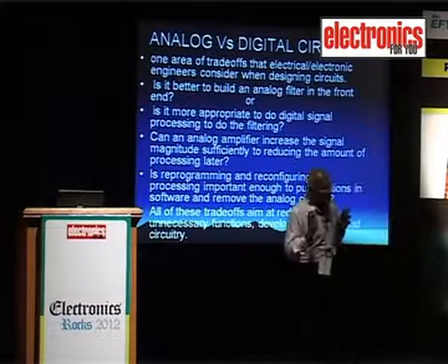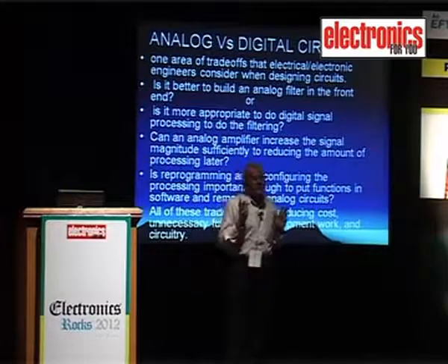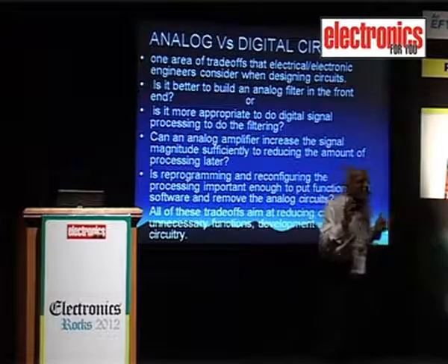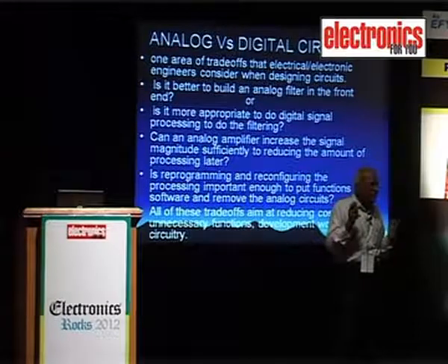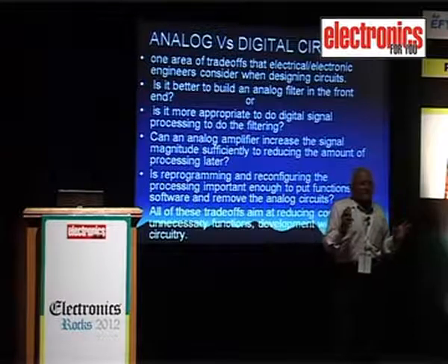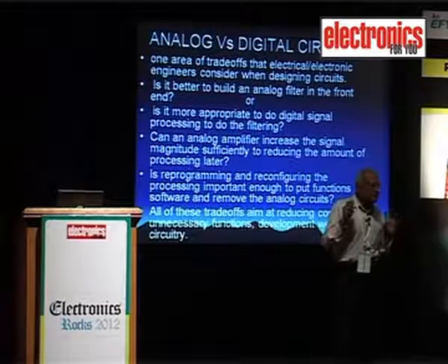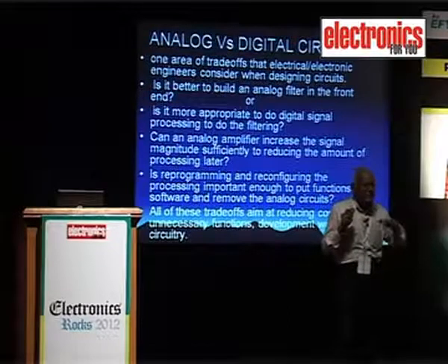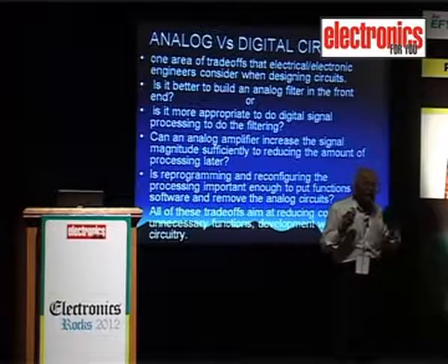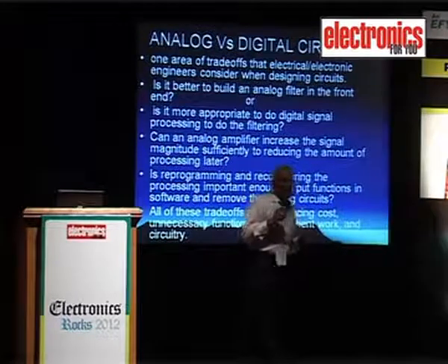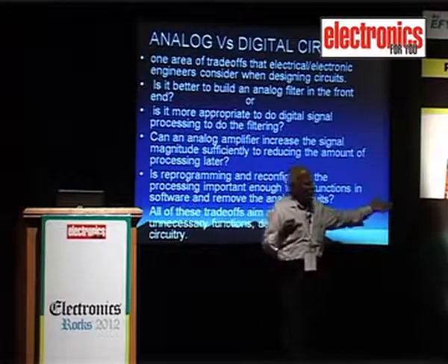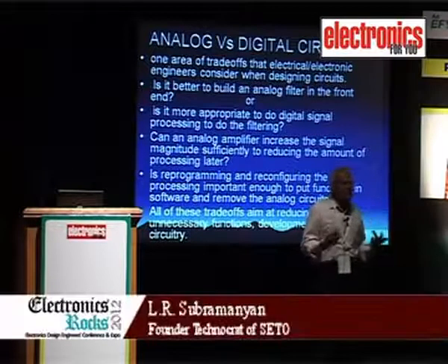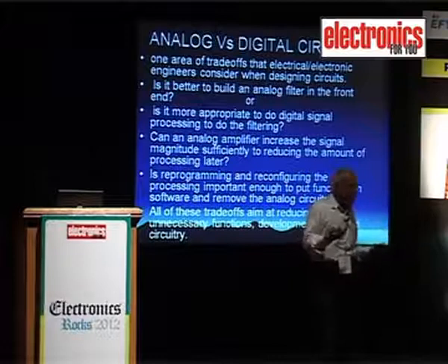So subsequently we realized that people do not know how to specify. If by chance the battery is not charged, the battery charger is off for any reason, AC is off, something has happened, the voltage can go down to as low as 38 volts. We have 51.2 volts on charge, and in the normal condition it is 49 volts, but it can go as low as 38 volts. As far as the client is concerned, I have put the battery on, your system is on, you have to ensure that your product works. So since then, we have been designing our equipment because we don't expect these guys to specify properly.